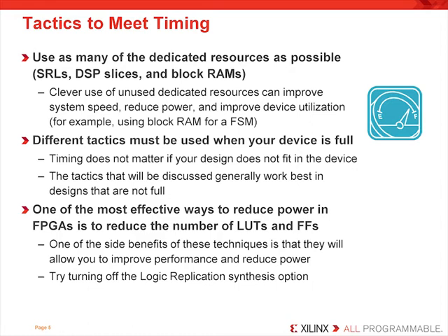Synthesis tools will try to improve the speed of a design by replicating logic. Logic replication is a synthesis option that allows the synthesis tool to replicate signals that have trouble meeting timing due to a large fan-out. This will generate more registers and can be a problem if you're running out of available resources. So, if you are already synthesizing with this option, you may want to resynthesize with the option off.